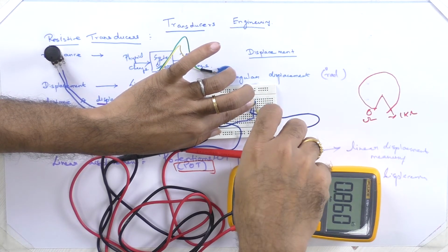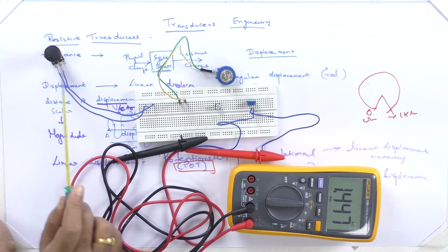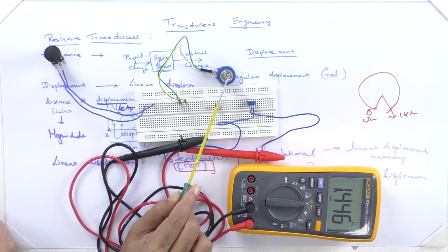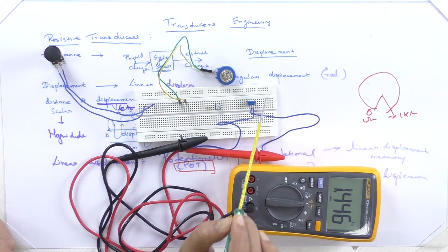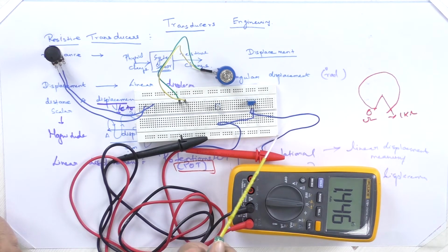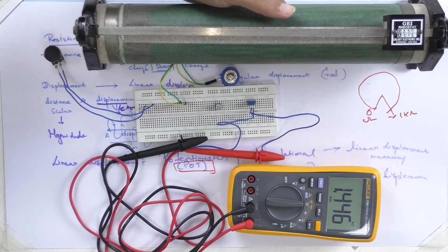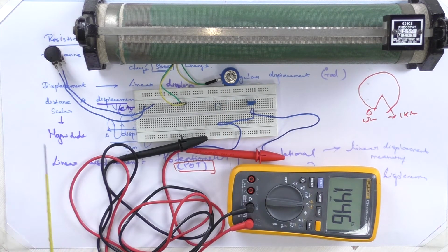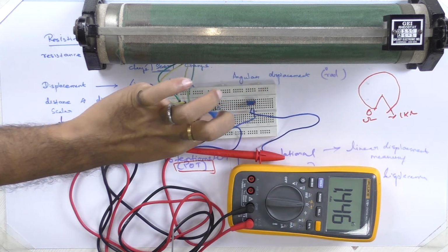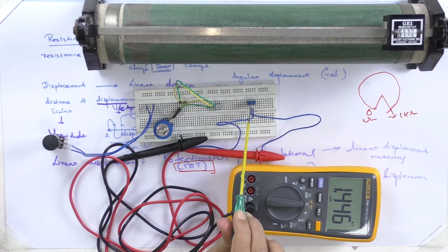These are very cheap, but they are not very precise. These are very precise and a little costly. These are cheap and also precise. So we use these in PCB boards. Now you have been introduced to many different kinds of potentiometers: our translational potentiometer, the rotational potentiometer, the helical potentiometer, and these single turn rotational and multi-turn helical potentiometers,